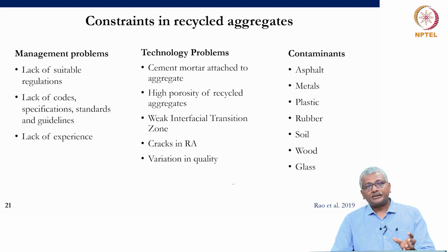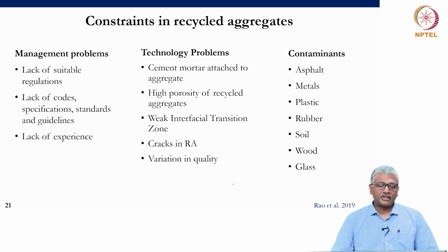Now, of course, those problems can be tackled by advocacy, by policy and so on and so forth, but technology problems are something that the engineer has to understand before utilization of such materials. One is, there is cement mortar attached to the aggregate and that has to be adequately understood. What is the extent of water absorption increase that happens because of this attachment of cement mortar?